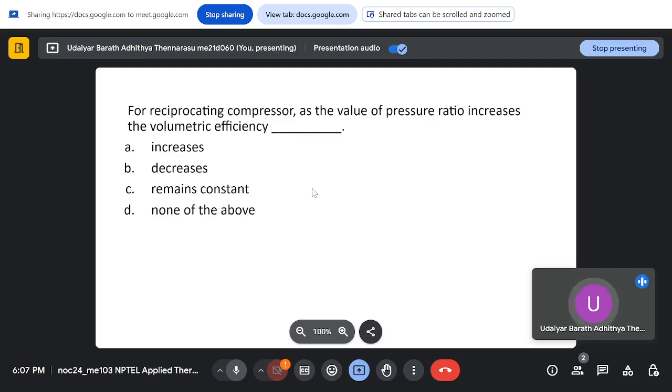So all the gases will not escape. There will be some amount of gas present inside your piston cylinder. When the piston moves down again, when the suction stroke happens, the initial pressure gas which has not left the cylinder will expand, and once it reduces to a pressure lower than your suction pressure, your suction valve will open, and the air or fluid will come inside.